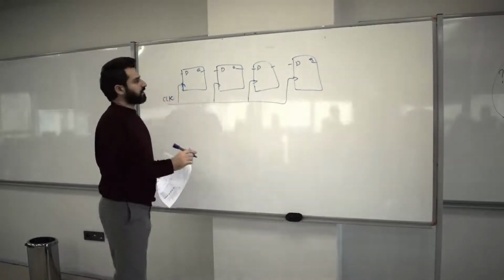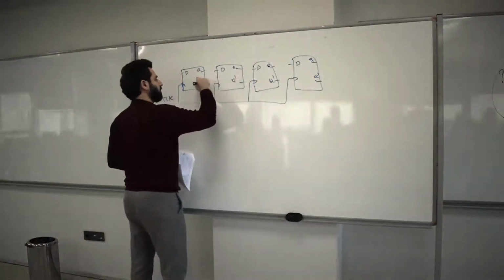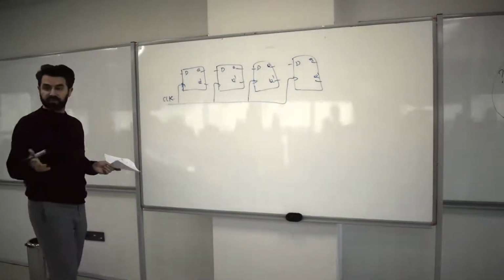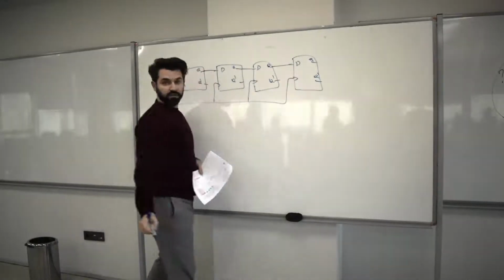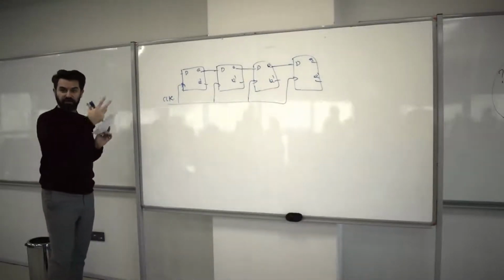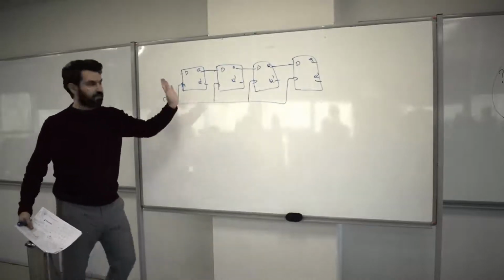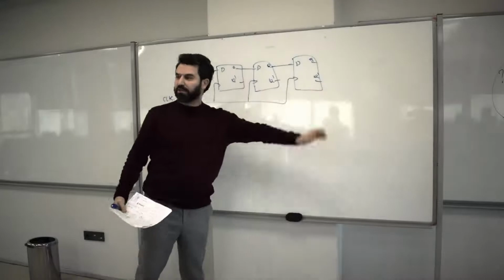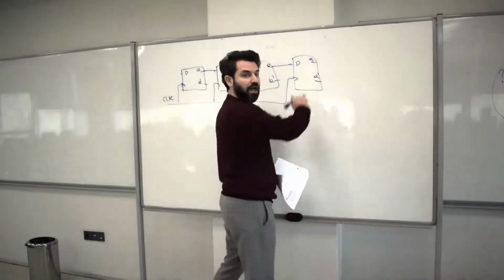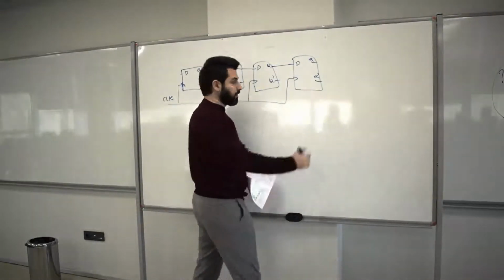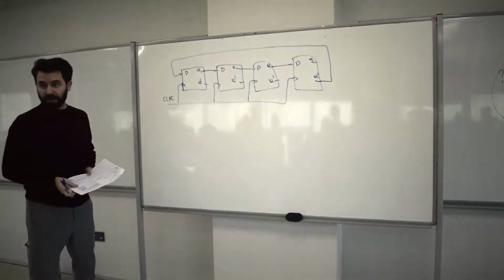So these are Q's, of course, and you remember that these were Q primes, right? One of the things that Johnson did was connect these Q's to preserve the shifting property. It still has to shift. As long as you have a clock, it will shift everything stored on those flip-flops to the right. So he preserved that. But instead of using the output of the last flip-flop from the Q output, he uses Q prime, and then feeds it back into D.